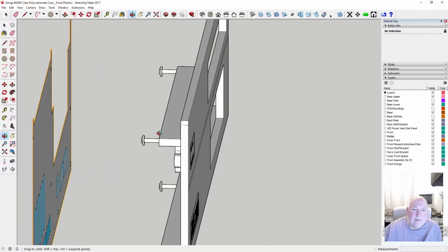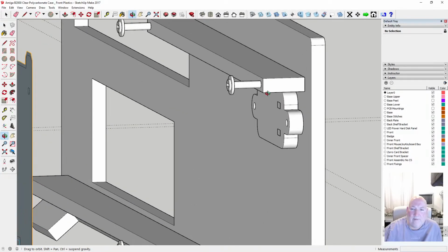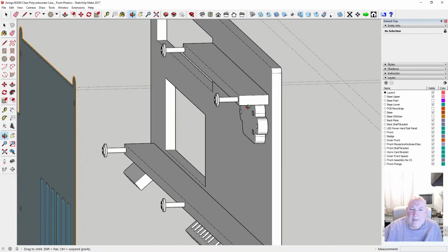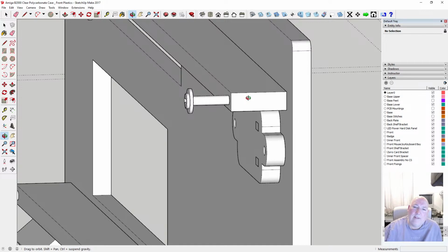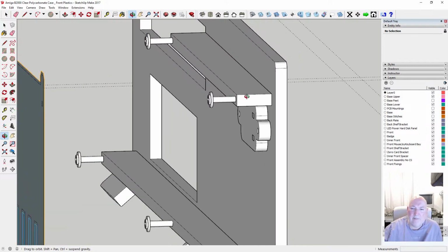These spaces, I can't, the 3-axis CNC can't cut this out and can't drill sideways. So how are we going to do it? We could pocket it, and then gravity would have to hold it in place until you tighten it up, but that doesn't make for a stable thing.